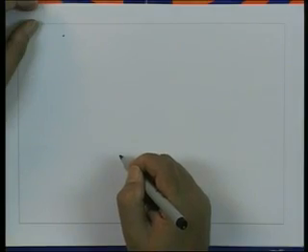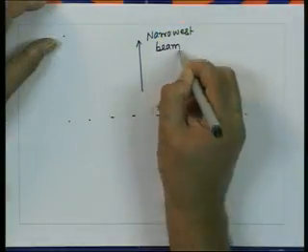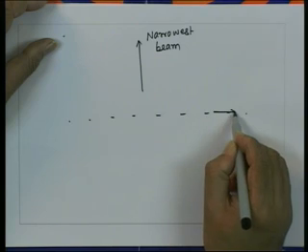So, for a given array, there are two things we have to observe now. One is that when I scan the beam for the phased array, let us say this is the array, I will get the narrowest beam in this direction and I will get the broadest beam in this direction.